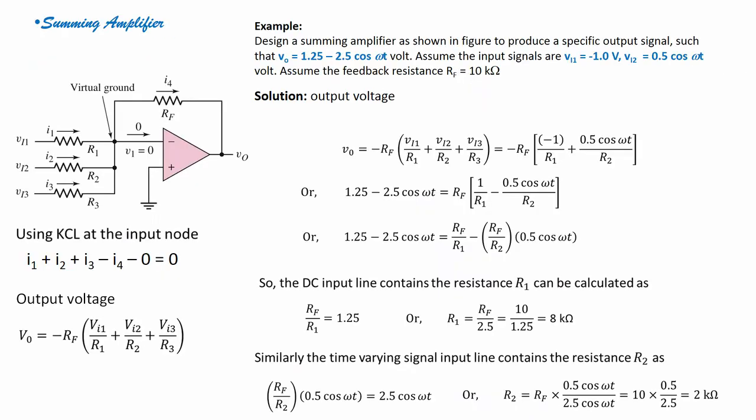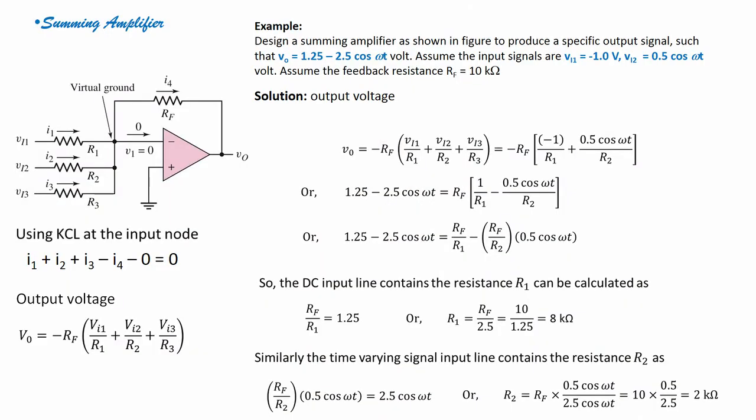Okay, guys. Now let us see an example of a summing amplifier. So, what is a summing amplifier? Let us see the circuit. When you see the circuit, we are using an inverting amplifier with a feedback resistor, but instead of one input resistor, you have 3. You can have n input resistors, so n inputs, and the output will be the summation of all the inputs.